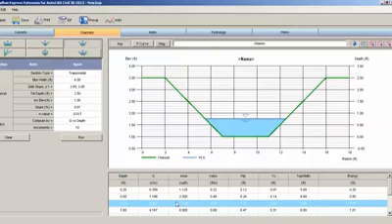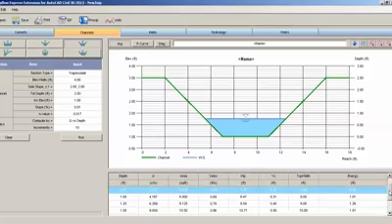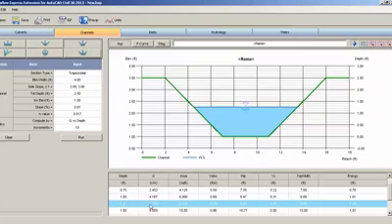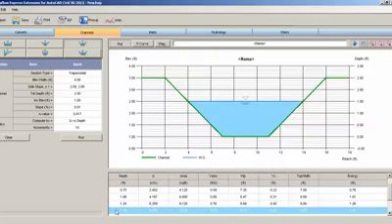The area is increasing, the velocity, the wetted perimeter also, and Y critical; all of them will be increasing according to the Manning equation. So here we have 1 foot, we get 4.167. At 1.2, we get a flow of 6.3. The flow is increasing because the depth is increasing also.